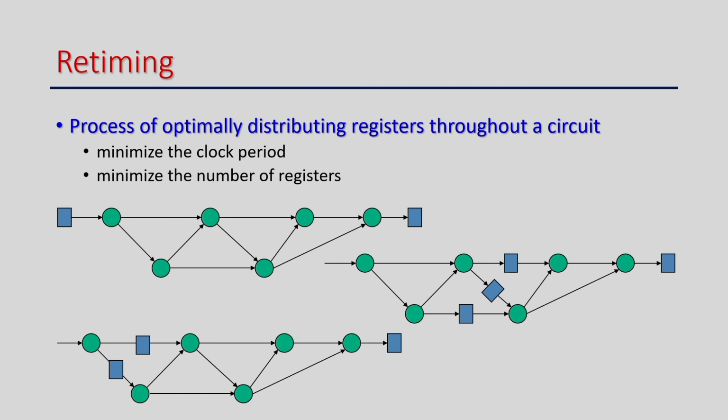So now I just try to see how I can apply these rules here. Suppose I want to move this register. As I mentioned, if I move it, it is only one input, so I can move it, but I have to move it into two output places, right. So this is what is done here. And then, say, suppose I want to move it further. If I try to move it further, what will happen? This is a single input to this node, so I have to move it to both places, right. So I can move it into both places, right.